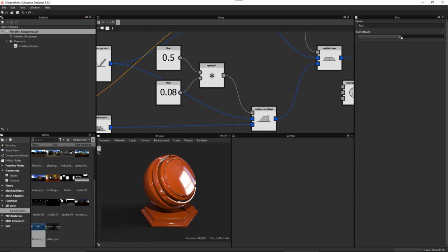If you've checked out our PBR guide, it's denoted there that the shader is remapped: at 0 to represent air, at 0.5 is actually going to equal 4%, and then all the way here at 1, it's going to equal this 8%. And that's why we have this float here at the max value. So what we're doing is giving ourselves this range to go from 0, to here in the middle 4%, and then here at the high end of the spectrum at 1, 8%. So let's go ahead and set this down here to 5.